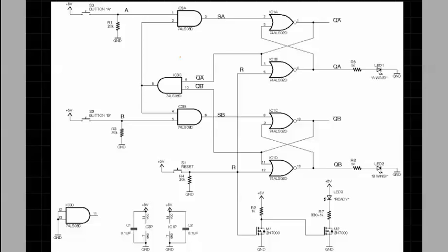So here's the basic idea of a Jeopardy switch. You have 2 switches right here, and 2 competitors, one assigned to each switch, and upon some signal, when they jump for a question or whatever, they'll push their button. This circuit will tell you which contestant won out, which one pushed their button first. So if contestant A went first, LED A will turn on, and if contestant B pushed their button first, the LED B output will turn on.